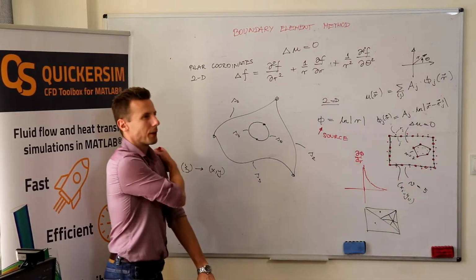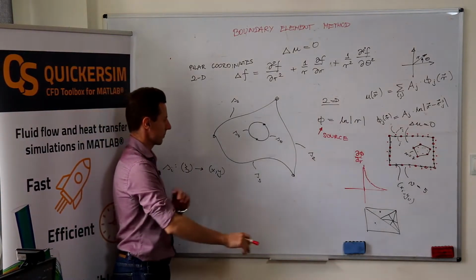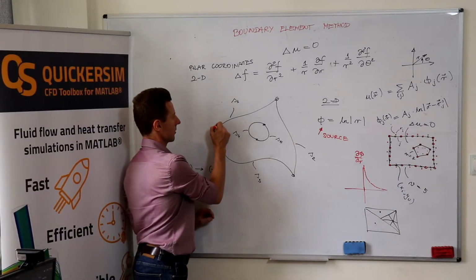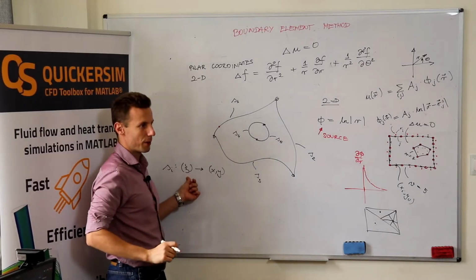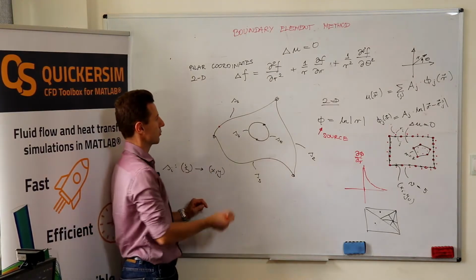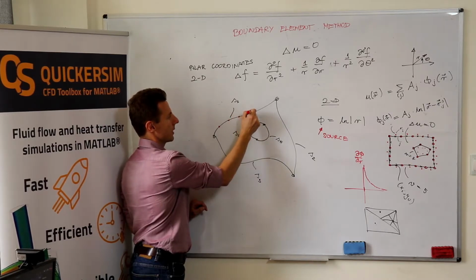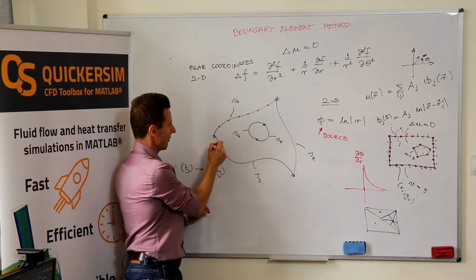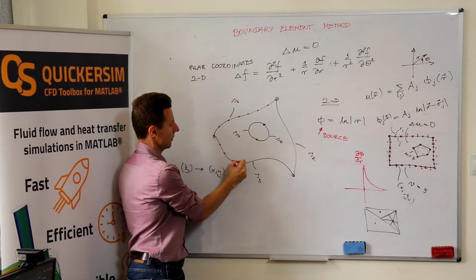If you've got, I think it's called, natural parameterization, then you can easily use that. It's very, very easy to subdivide it into, let's say, 10 intervals. Then with the natural parameterization, you've got the guarantee that these points will be equally distributed along the curve. It's very, very easy to do it for each of these 5 curves.